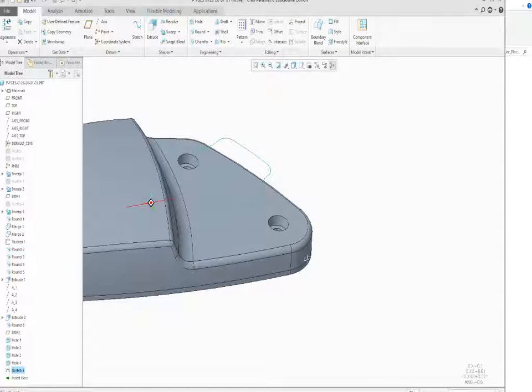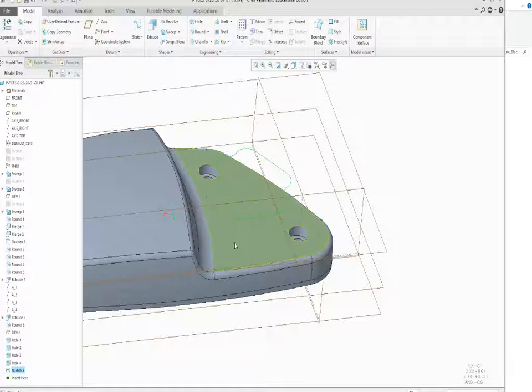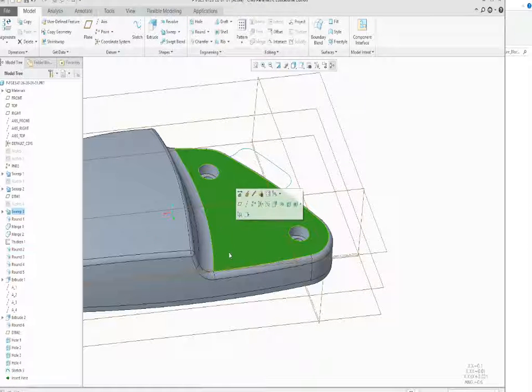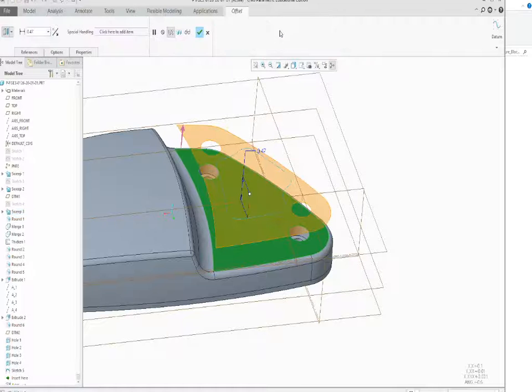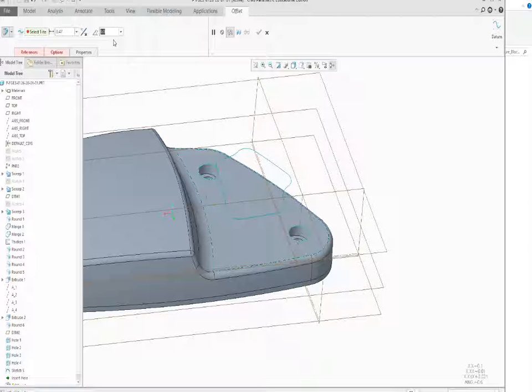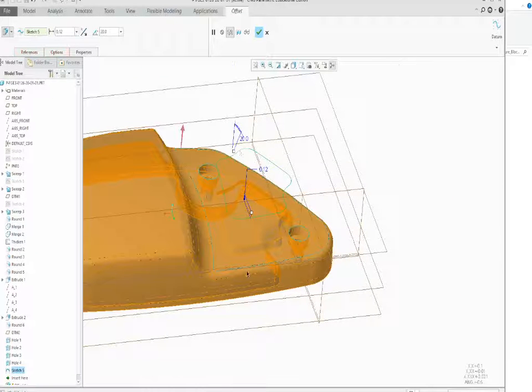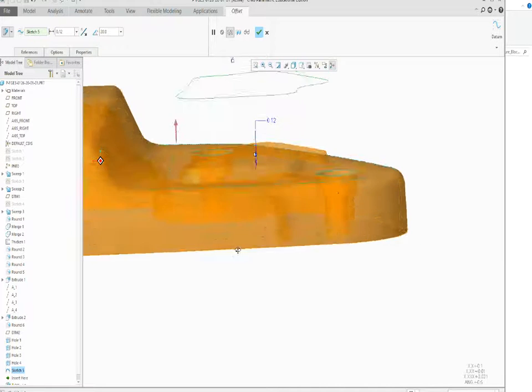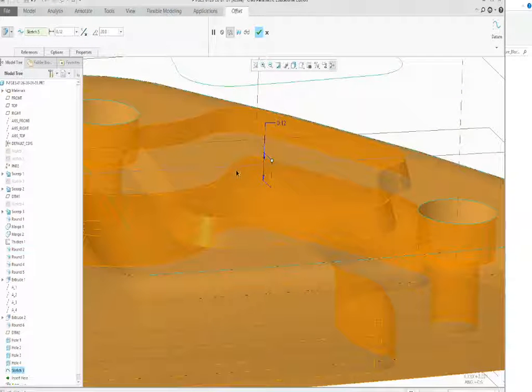Now, once we touch this right here, now we've got the profile. We have to touch the surface that we want to do the profile on. So we touch here. Once we've got the touch, then we can hit offset. Next thing we must do is switch over to taper. So we switch to the taper mode right here. We want to move this thing to, let's say, 20 degrees. And then we select inside this box and grab the sketch. When we do that, we're going to see our tapered surface come up. If you do not, a lot of times it's because your sketch is corrupted.